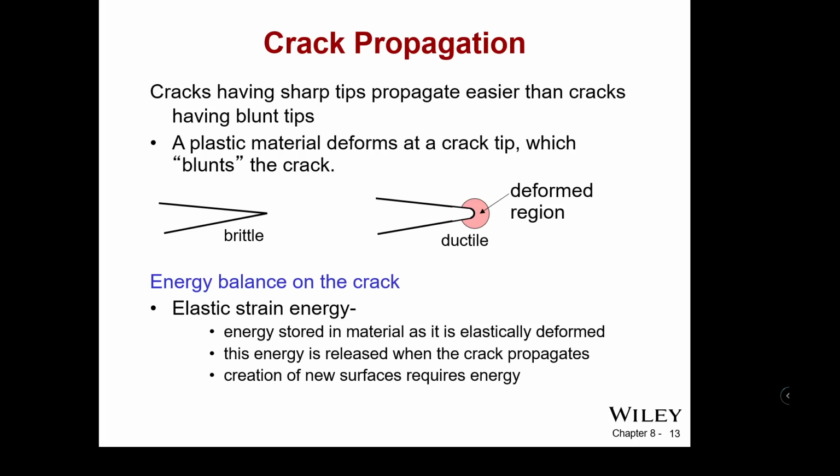So the deformed region in the ductile sense becomes less and less sharp. That deformed region at the edge of the ductile crack becomes sort of blunted, because the material is stretching at that point rather than simply breaking immediately.